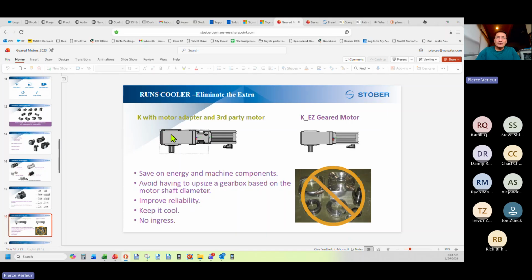And again, if you're intermittent duty, assuming you're not blasting the thing with a whole bunch of high peak torques, then you're going to get more than 3 to 4 years. But the differential between the two means that one's going to fail before the other one, and therefore you have to account for that ease of replaceability.